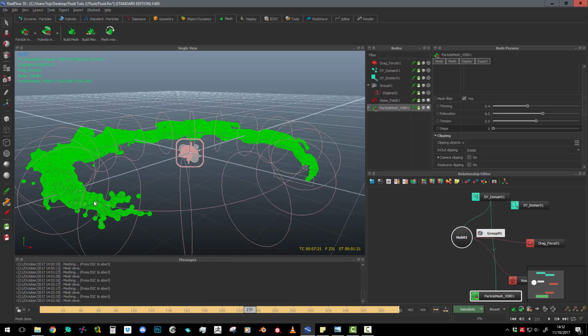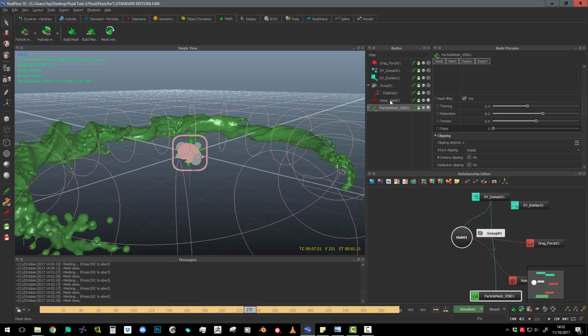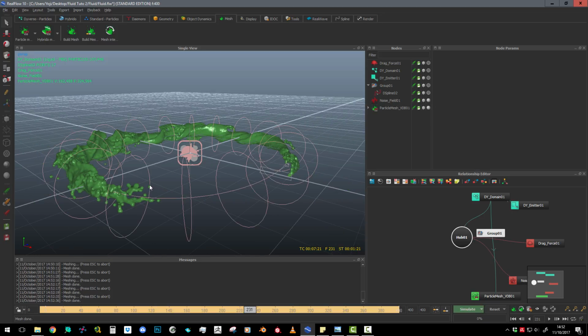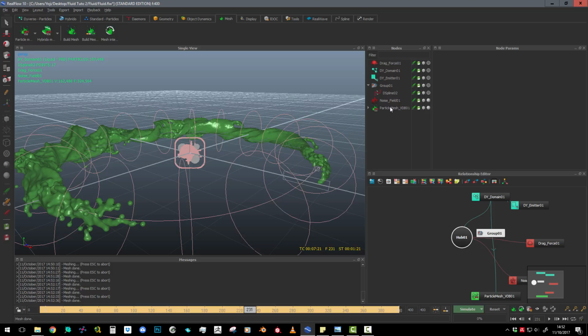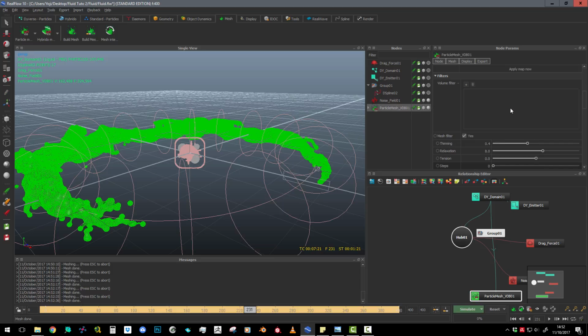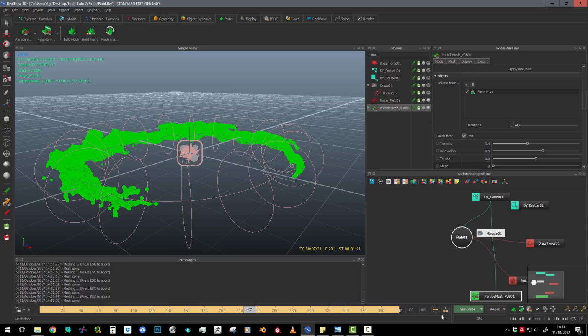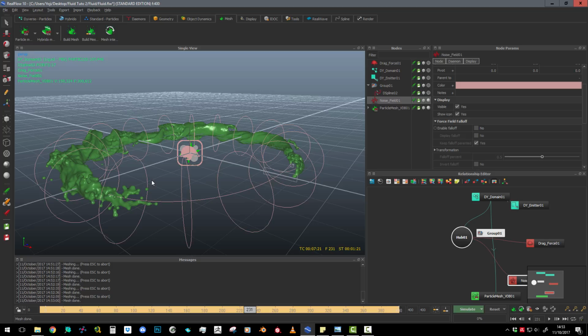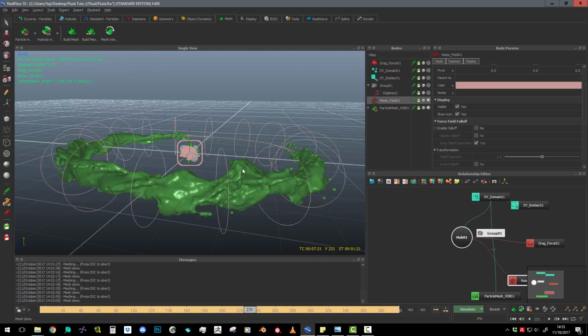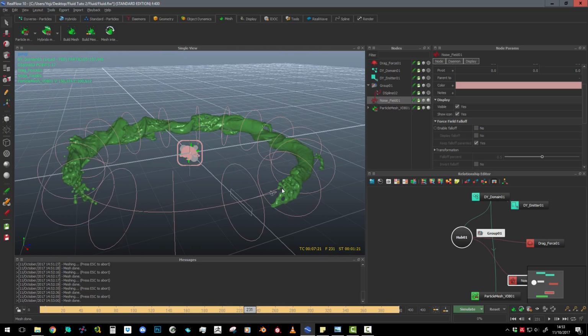Okay, so it starts to be already better. For me it looks more like liquids already. And maybe we can use a volume filter too. In this section you just go to plus and add a smooth filter and change the meshing again, and now it looks far better than before, and it looks more like liquid now. And we will use this setting for all the simulation.